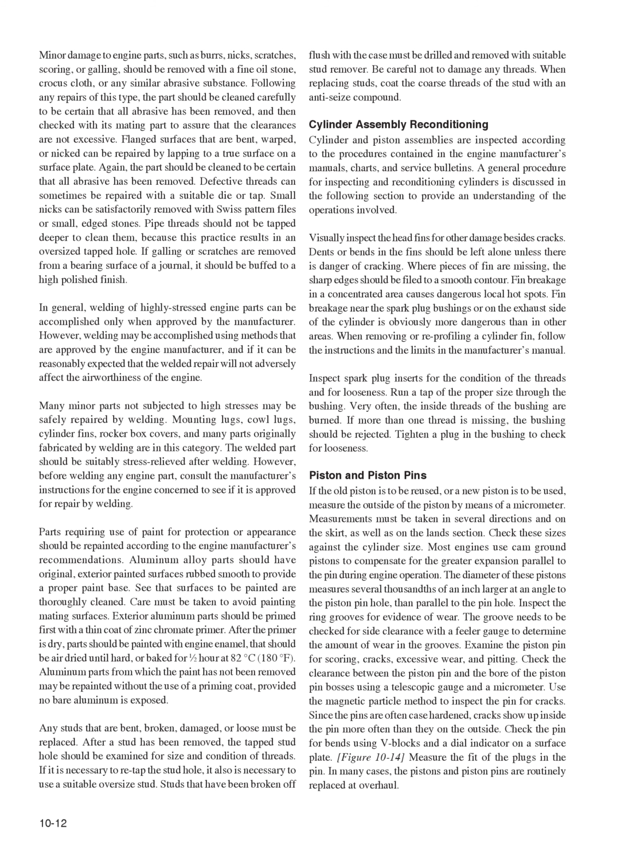Piston and piston pins. If the old piston is to be reused, or a new piston is to be used, measure the outside of the piston by means of a micrometer. Measurements must be taken in several directions and on the skirt, as well as on the land section. Check these sizes against the cylinder size.